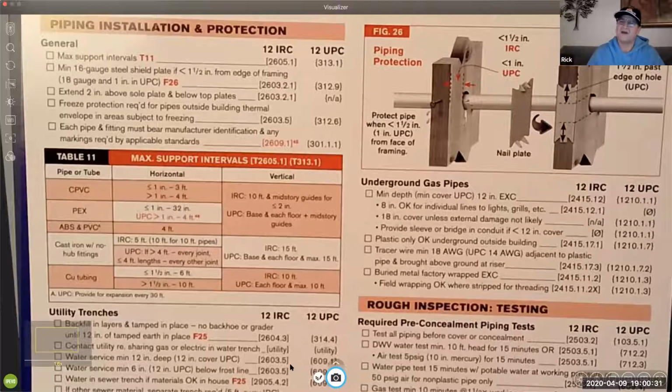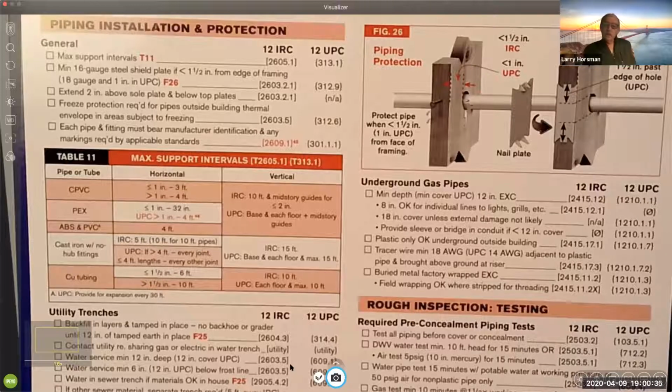Oh, so the metal plate has to extend up 1.5 inches past where the actual hole is? Right. Okay. Yeah, you can see, because of the red arrow there. They make those plates in a number of widths. Occasionally the inspector is paying more attention to it than you may be, using short plates because that's what you have, hoping you'll get away with it.